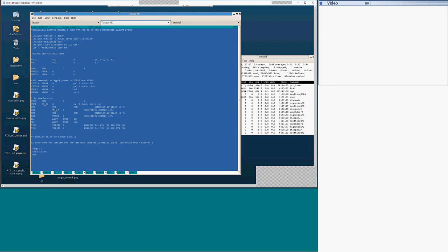And this one, I see it just probably remains intact. And for this, in 0, in 1, at the bottom, these are signals, so they were left intact. Signal waveforms are okay. And we instantiate a circuit, that is essentially the DSPF subcircuit. And there are statements like temperature, transient simulation parameters, and that's it. We do not require anything else on top of this.